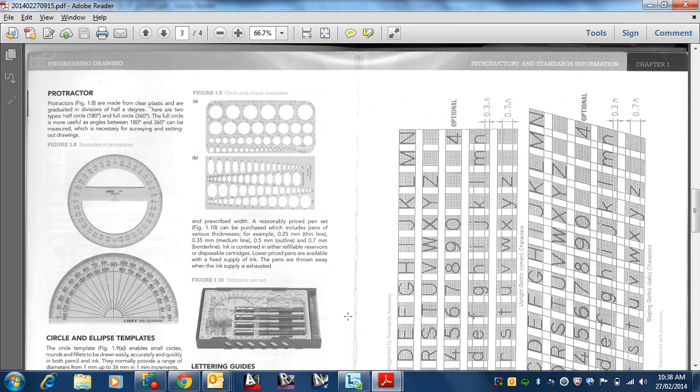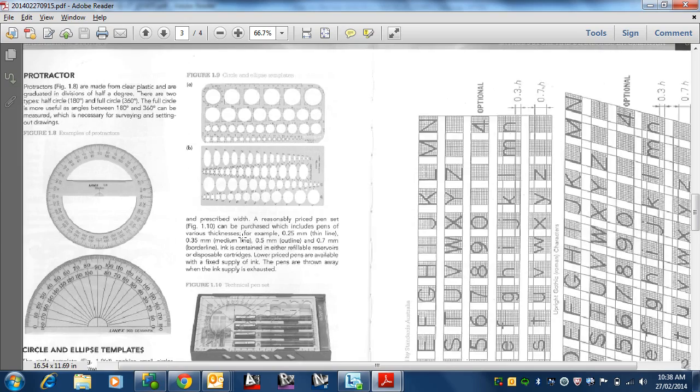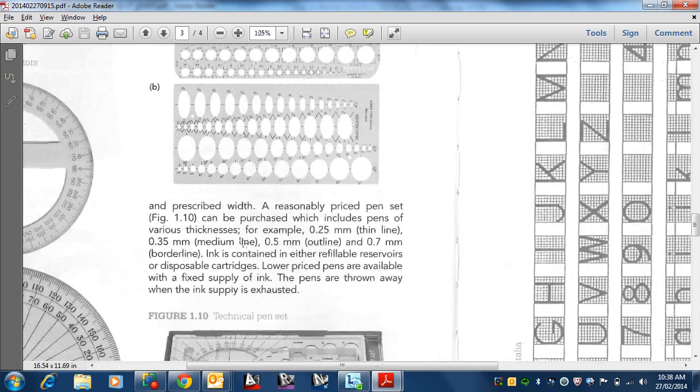Notice there are only 4 pens, generally because that's roughly what we want to end up with when you print out a drawing. Depending on your field, in mechanicals not so much, the minimum, I think, is 0.25, so you probably wouldn't get a 0.18, for example. 0.25, 0.35, 0.5 and 0.7 are the general pens listed, and you can read that there.